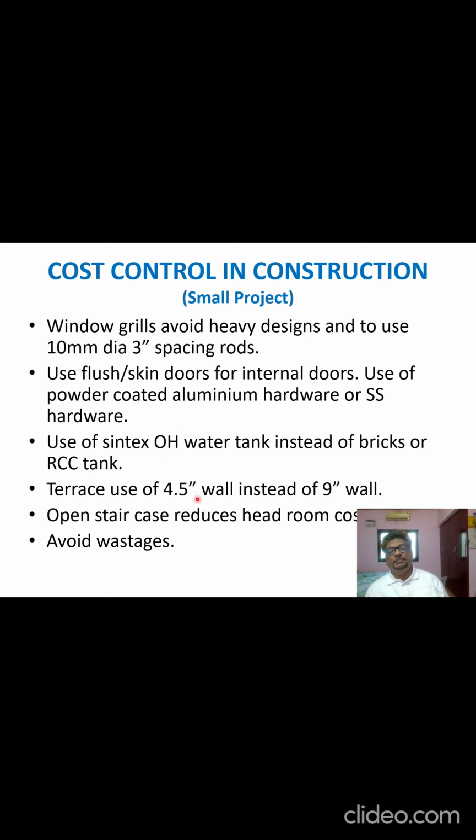Terrace parapet walls can be constructed with a 4.5-inch brick wall or a 9-inch wall. As per your requirements, if the future expansion is not immediate, you can go in for a 4.5-inch wall as well. You can use an open staircase so that it reduces the headroom cost. If you use the open staircase, the headroom cost can be avoided.